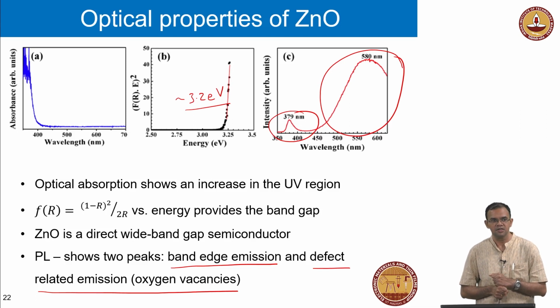Questions? Adding doping or removing the defects? Usually doping is better because you can always control it. Defects are much harder to control, and you cannot increase defect concentration very high because there's always some thermodynamic equilibrium that has to be maintained. So especially when you want to change charge carrier concentration, doping is better.